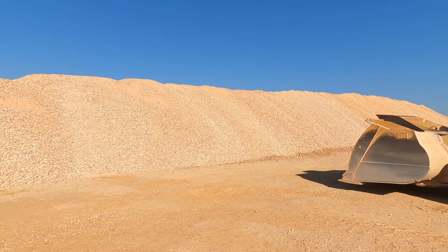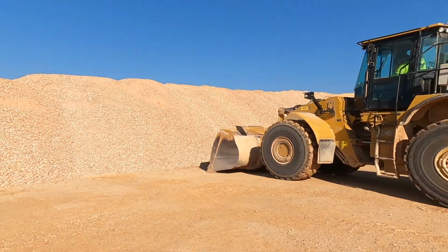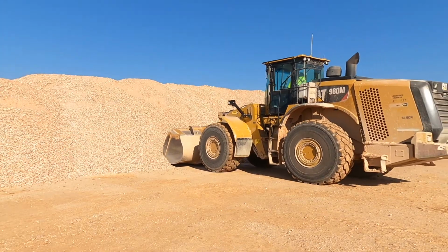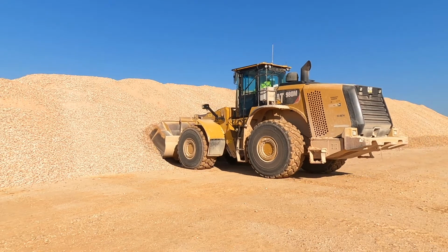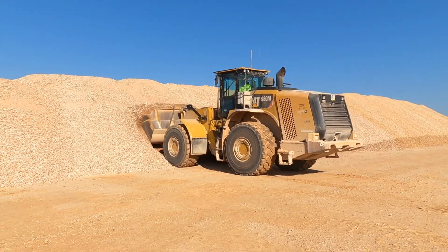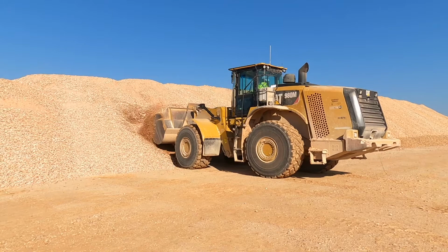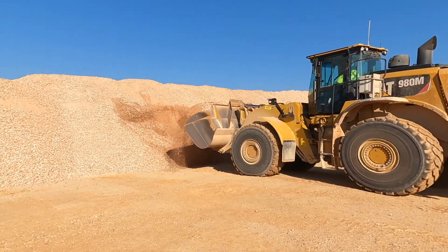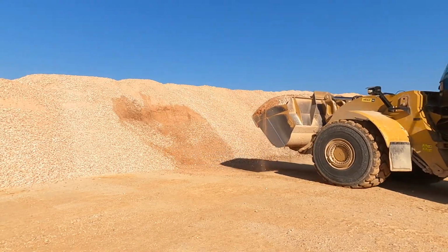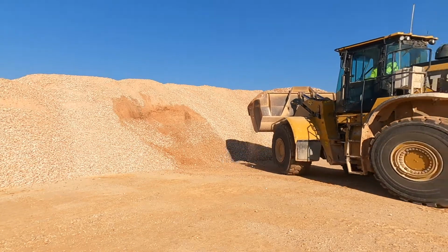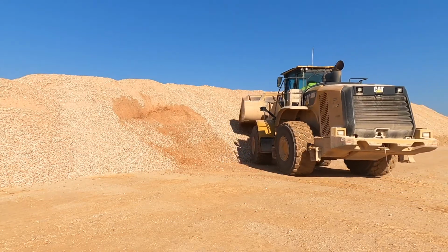Sample each quarter point of the stockpile using a front-end loader. Cut at the ground level to the top edge of the stockpile until a clean vertical face is exposed that is perpendicular to the top edge of the stockpile. This represents the full height of the stockpile. Discard this material cut away while exposing the clean face.